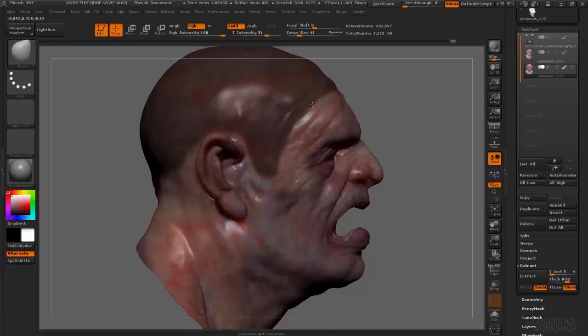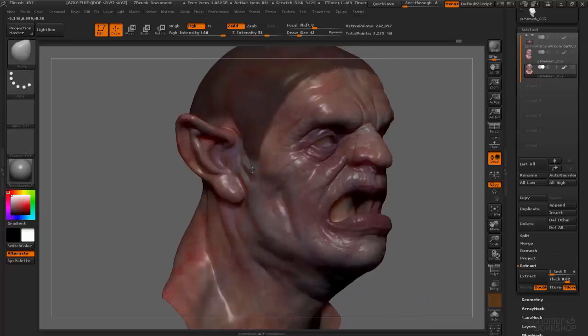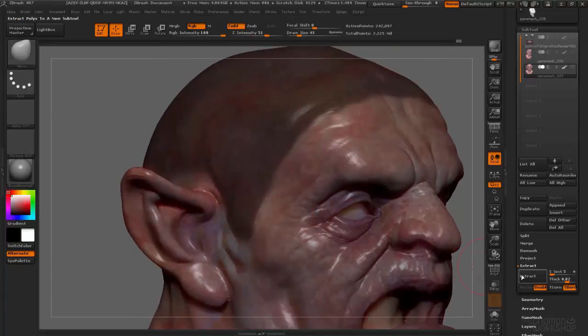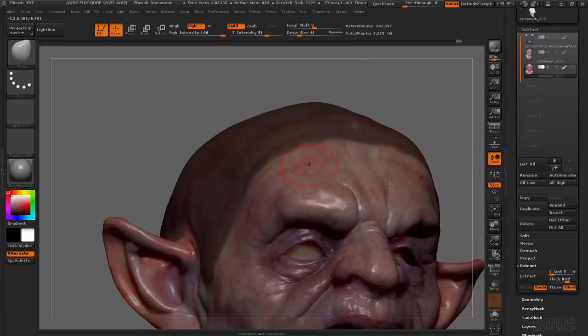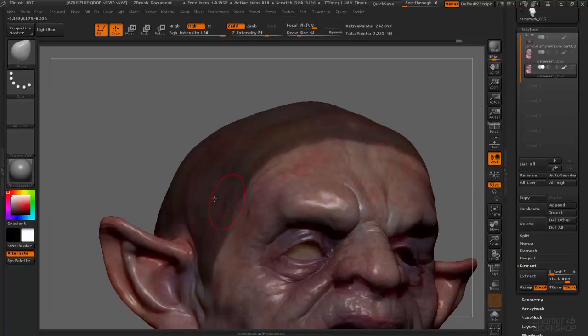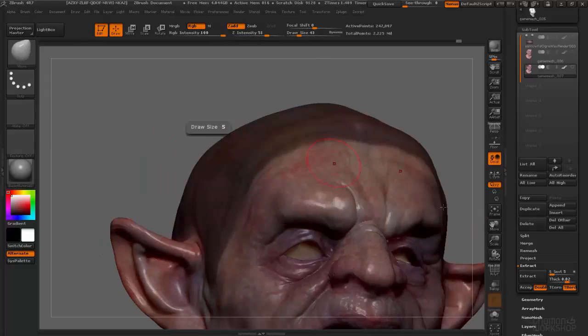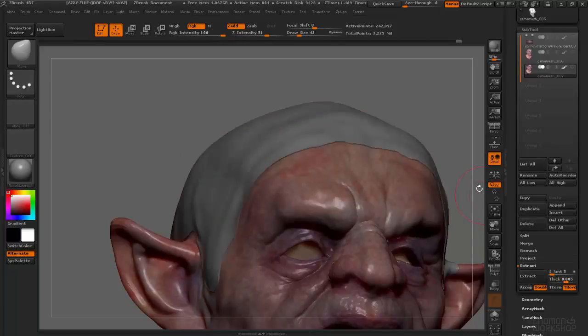I can paint out of the mask just like you would any other mask with Control-Alt, click and drag. Now I'm going to zoom in so I can see the edge of my extraction, and I'm going to press the extract button. And you see it creates an extraction based on the thickness setting here. Now if I feel that that's too thick, all I have to do is just change it. So if I move the model, that model disappears. That's because this extraction is not geometry yet. It's just a preview. I can come in here and set my thickness to 0.005 and then do the extraction again, and that gives me a real thin fabric-like form there.